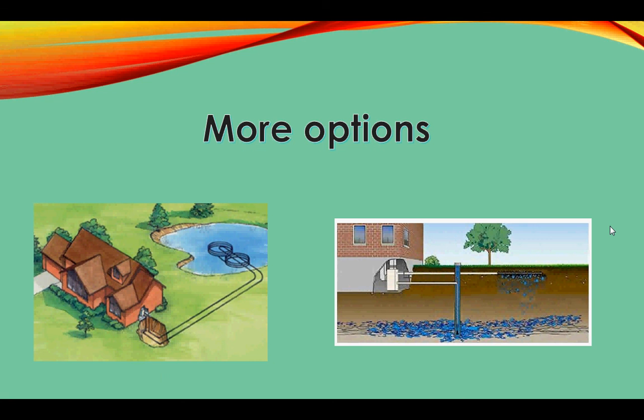Other methods are less common due to their unique needs. On the left, the submerged. No trenching is required, but you must have a lake of sufficient depth. The loops are held by concrete weights at 6 to 8 feet below the surface, because at this depth it is not likely to freeze. If your lake is not a sufficient depth to ensure that it does not freeze during the winter, this is not an option for you.